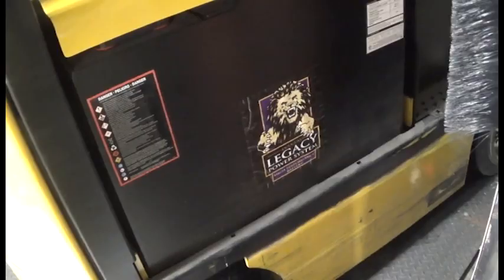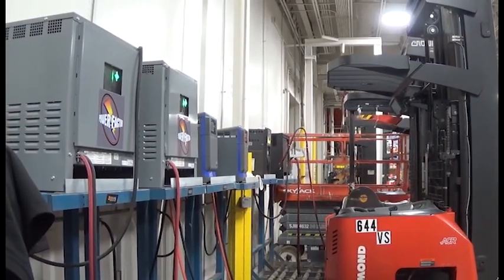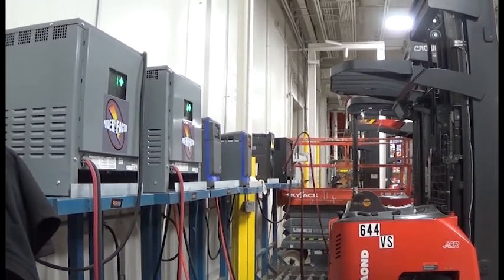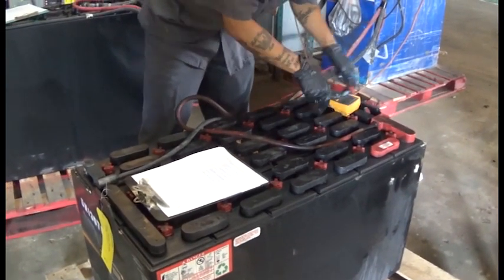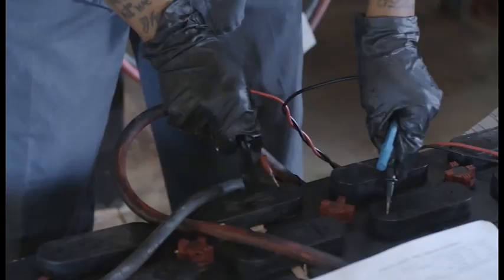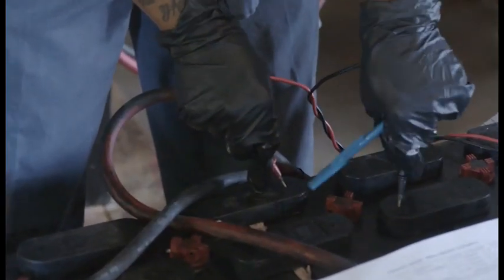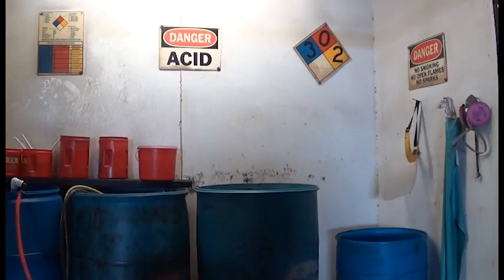Electric trucks use an onboard battery. A designated battery charging area should be established, and appropriate PPE must be worn when charging or maintaining a battery. Only trained personnel should charge and change batteries in electric forklifts. They should also be trained on emergency procedures in case of an acid splash.